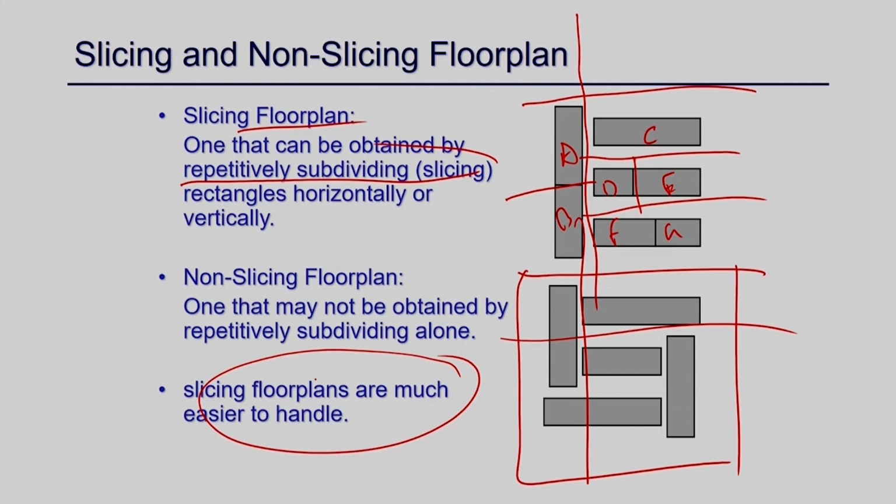It is generally good practice to make a sliceable floor plan. In such a way you make the connections so that you get a sliceable floor plan, and we will see that a sliceable floor plan is easy to handle for placement, routing, and all other components. So, usually the kind of floor plan we try to generate is sliceable, right. Let me repeat: sliceable is something where we can bipartition each sub-component at a time to generate the layout plan, in any order, horizontally or vertically. Okay. So, these are some terminology that you should be aware of during floor planning.